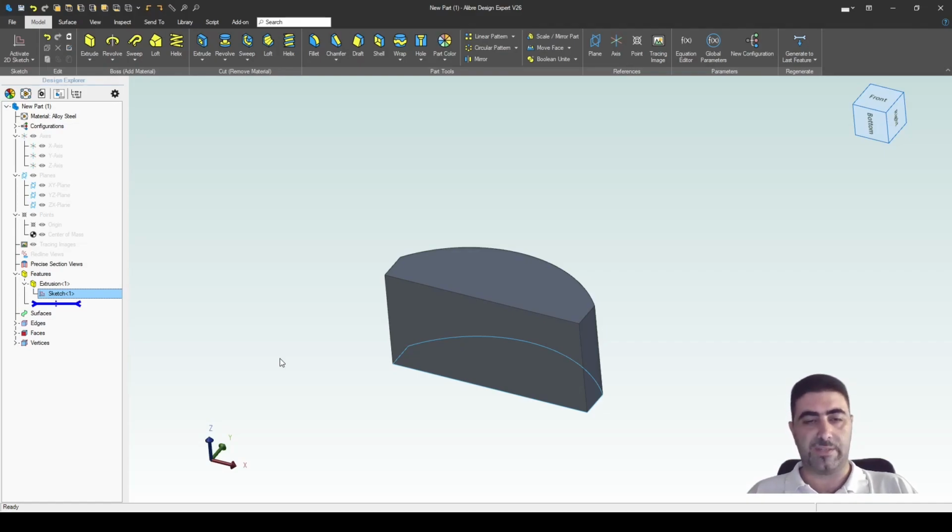If, for example, there's an opening where two corners are not connected, then the water will flow out, as it were, and that's not a watertight sketch. If you're curious about why that is a prerequisite in any parametric CAD system, it is because your sketch is defining the boundaries of the manifold that is going to be created.